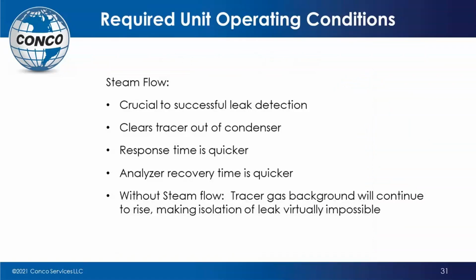And this is for, I don't care what kind of condenser, steam or an ACC unit. What you're trying to do here is make the helium move throughout the system. You want to drive it from your entry point throughout the system so you find the leak. Otherwise, the helium just finds pockets, and that pocket of helium will just sit in that location. Eventually, it will leak somewhere, and you'll get a false leak, but you'll never really find the proper leak.